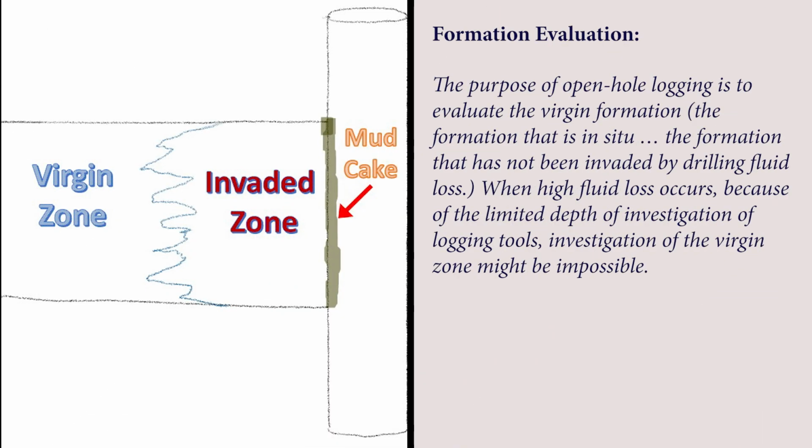5. Formation evaluation. The purpose of open-hole logging is to evaluate the virgin formation, the formation that is in situ, the formation that has not been invaded by drilling fluid loss. When high fluid loss occurs, because of the limited depth of investigation of logging tools, investigation of the virgin zone might be impossible.